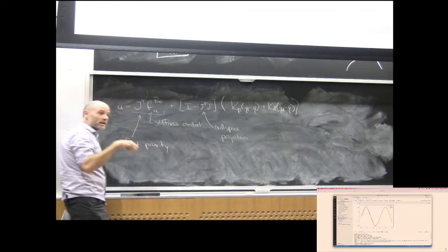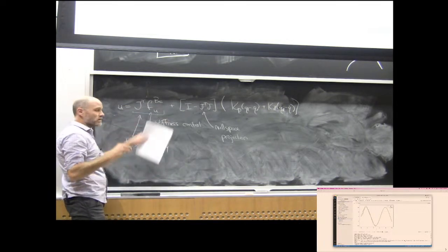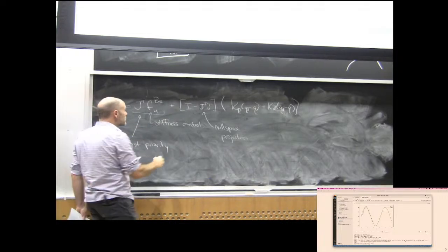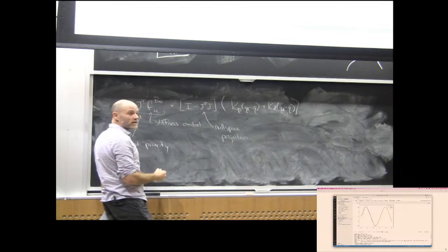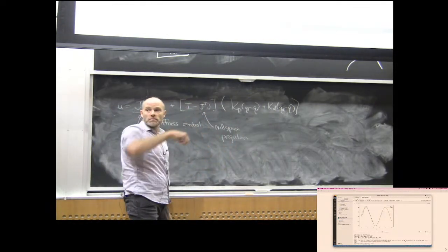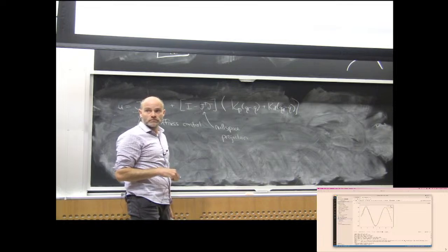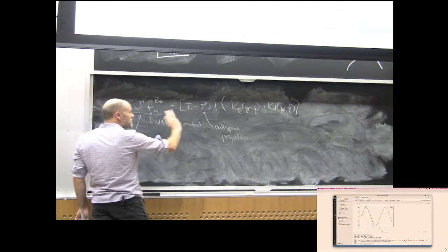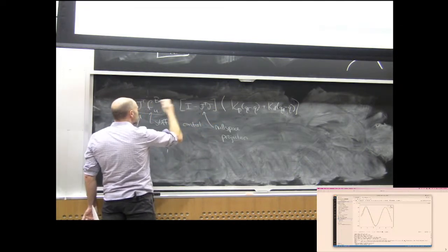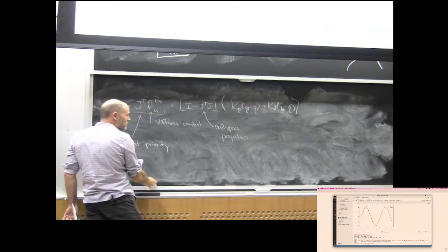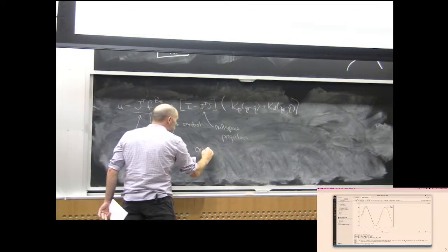The torques you pick should absolutely create the virtual stiffness that you want at the end effector. But in the null space of that Jacobian and any extra degrees of freedom, I'd like the rest of my joints to act like they're a PD controller going back to the original. Okay? And this mixing of joint space and end effector space control was originally called operational space control.